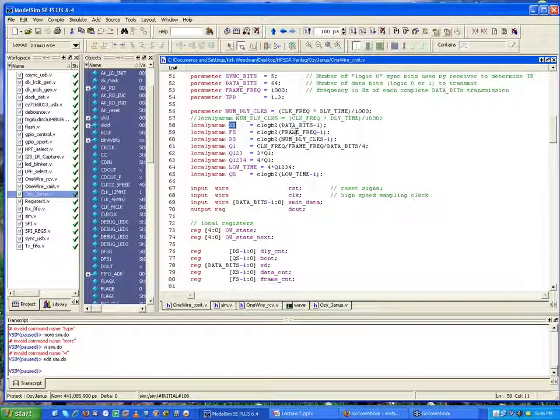So if it takes 6 bits to hold the value of 63, then I'm going to create a register down here called data count, going from 0 to xs minus 1, 0 to 5 in this case, which is 6 bits. Now I can define my register width to the minimum required for this module based upon the parameters. It looks a little strange, but it's real handy. That way you don't feed it an excess of bits and a bunch of flip-flops that never get used. Here I've defined just the number that I need. Does that make sense? Yeah, that's slick.